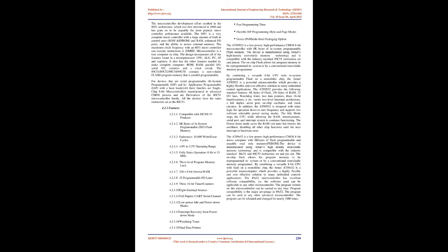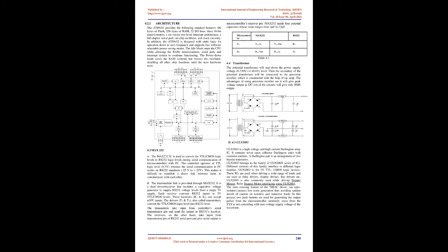The AT89S52 is a low-power, high-performance CMOS 8-bit microcontroller with 8 KB of in-system programmable flash memory. The device is manufactured using Atmel's high-density non-volatile memory technology and is compatible with the industry-standard 80C51 instruction set and pinout. The on-chip flash allows the program memory to be reprogrammed in system or by a conventional non-volatile memory programmer. By combining a versatile 8-bit CPU with in-system programmable flash on a monolithic chip, the Atmel AT89S52 is a powerful microcontroller which provides a highly flexible and cost-effective solution to many embedded control applications.